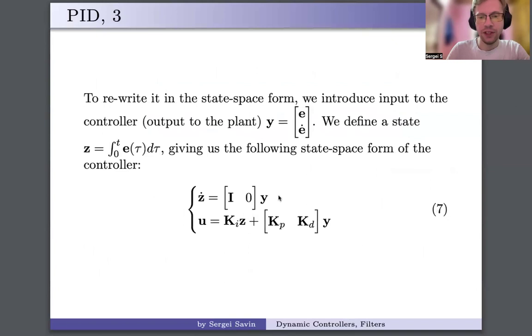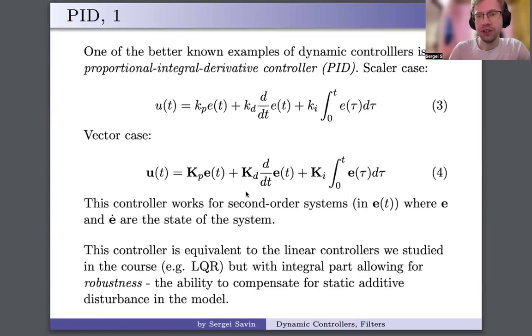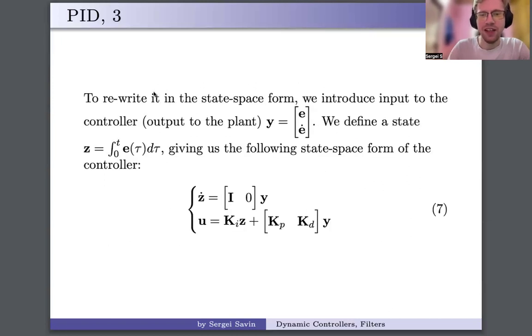So what does this knowledge give us? Well, of course, we need to understand that PID would contain a state, so we would need to store something on the controller. That should be quite obvious because of the integration here, right? This integration would imply that by doing numeric integration, we would store something. That's how numeric integration works. But it's not an artifact of the fact that we do numeric integration. It is the nature of the controller being dynamic, right? That is a difference.